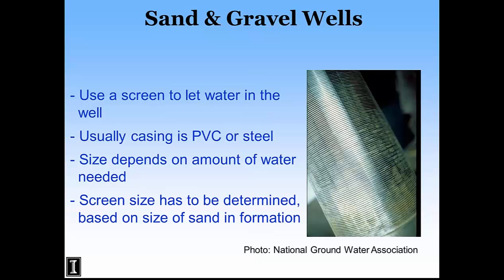So a sand and gravel well, I mentioned, has a screen. And so this is a well screen, a picture from the National Groundwater Association. It's slotted. It's called slotted screen. And the slot size is determined based on a sieve analysis of your sand and gravel, typically. Now, some drillers may have drilled 6, 7 wells within a half a mile of where your well is, so they already know what slot size to use based on that. But usually you need to size, it depends on the size of the sand grains, how fine the openings are, and how narrow the openings are. Again, that's to protect your well from having sand get through those slots and then interfere with your pump.